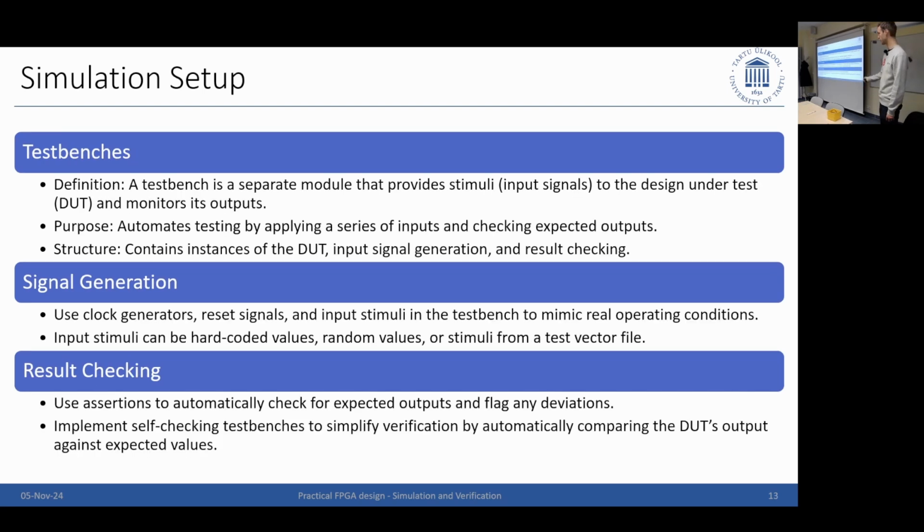Although it can still happen, because your design files might change, and then you need to change your test bench again. So it might actually be a loop, but at a more advanced experience stage, you want, of course, to avoid this kind of loop. Also, when you have proper requirements, you will have to generate the signals in a certain way, and you may not be able to change it. So if I know I get Ethernet data in, I will need a test bench which simulates the Ethernet protocol. There's nothing I can do about it, right? That's set. So I have to write a test bench which sends me the Ethernet data, and I then need to properly accommodate that.